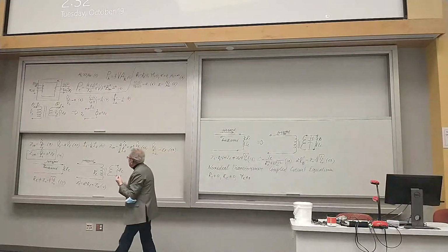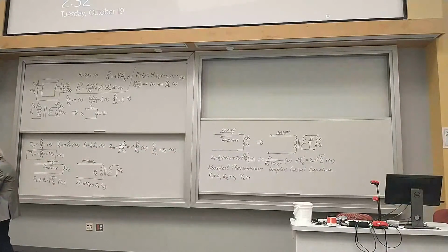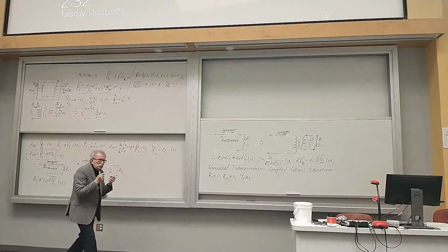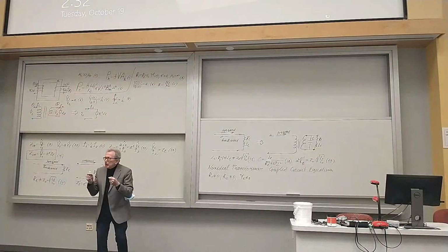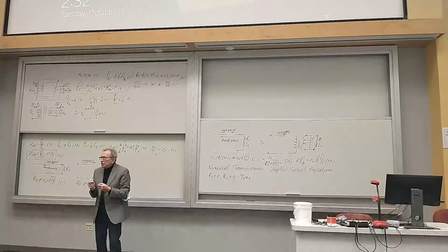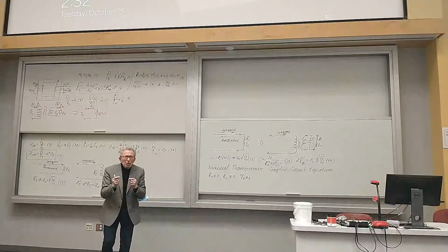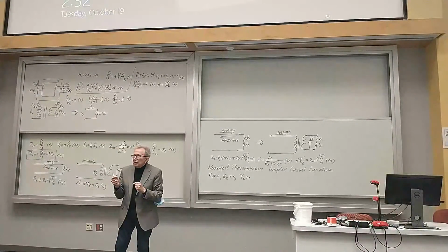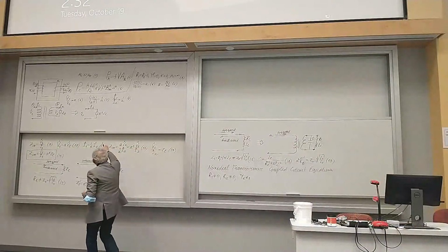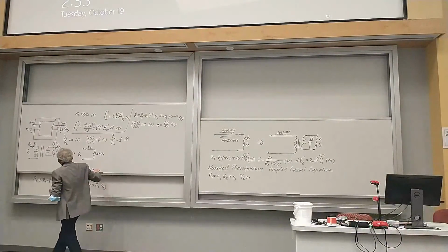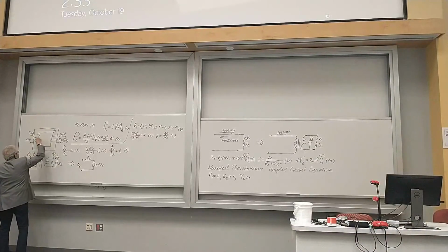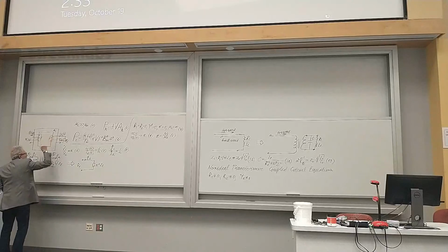As I pointed out, in the case of the transformer, we deal with a high magnetic permeability magnetic core. Because of this high permeability, the majority of the magnetic field lines will be confined to the ferromagnetic core. However, a very small number of them will leak out and go through the ferromagnetic core and air.